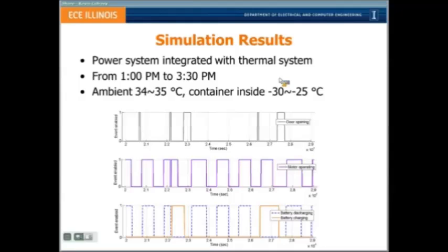So you're charging it from the diesel engine, but the diesel engine is also always on? The diesel engine is not always on, only when it's starting up and moving. Right. And then how does it know when to charge it? Does it detect the state of charge? Right. It has a preset limit, like below 0.95 state of charge, or the system commands it to charge.